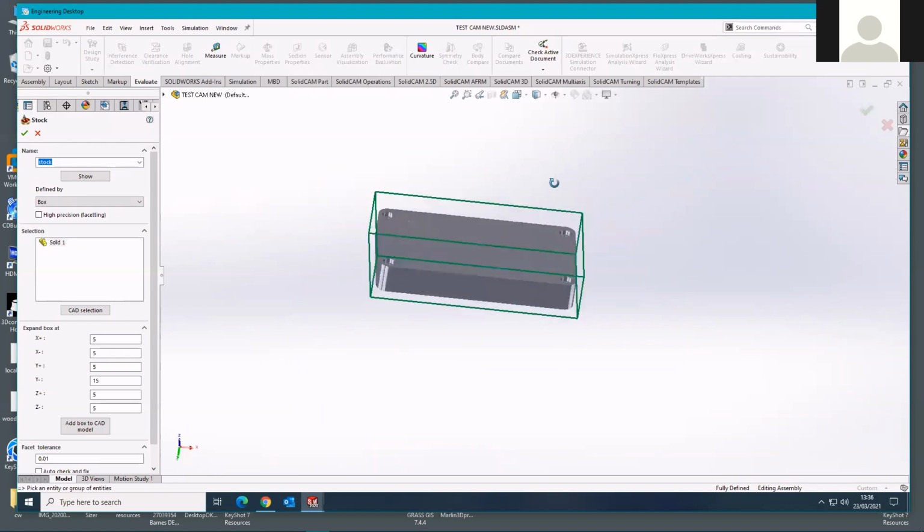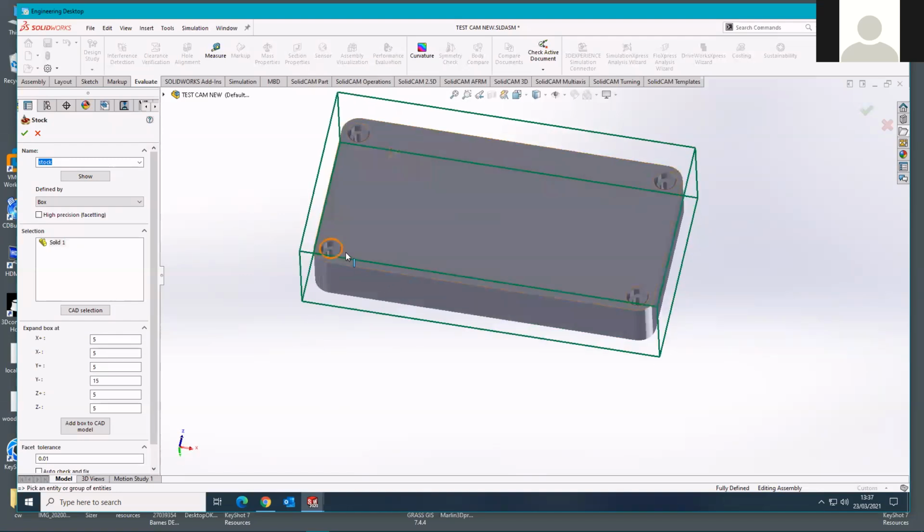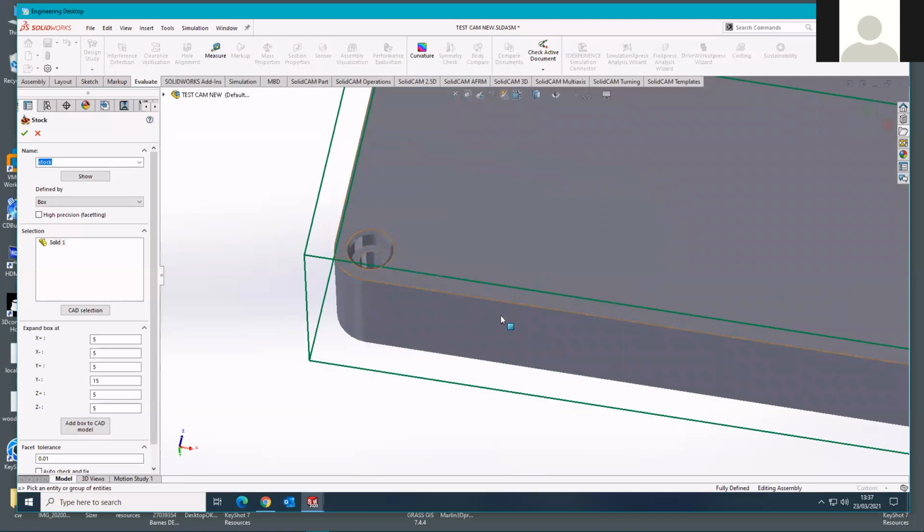I think when I discussed this with the CNC operators in chief, they had a few suggestions. One was you could use a vise again. You could just put soft jaws on the vise so it didn't damage the machined faces that you created on the box. Or you could create a plate which is bolted into the CNC machine, which is essentially a jig. And then you could locate on the jig using some of the bolt holes.